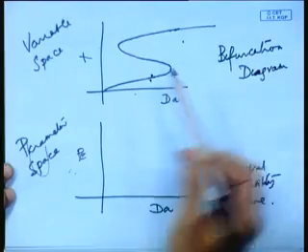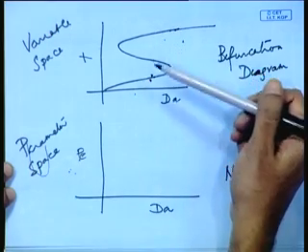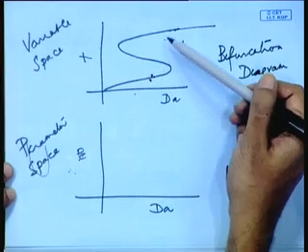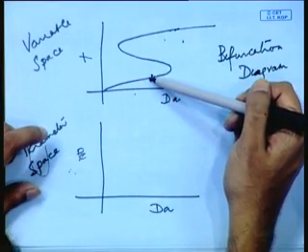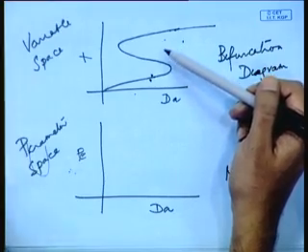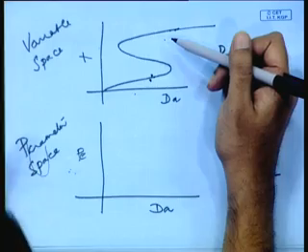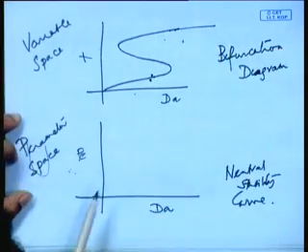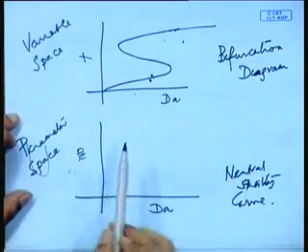If you look over here, as we discussed, the bottom leg is stable, the top leg is stable, but the middle leg is unstable. So even when the system is stable, there is still a possibility of it being in the ignited branch or in the extinguished branch, and you want it in the ignited branch. I'll come to that also, how to figure that out. But your first criterion is stability. Now you tell me, I have explained so much, how do I draw my neutral stability curve?